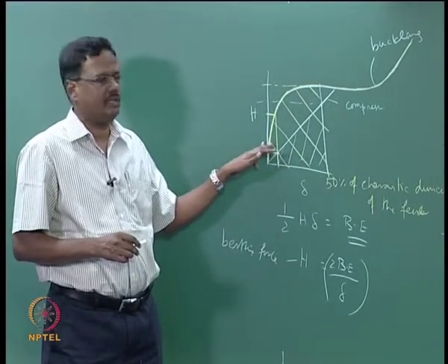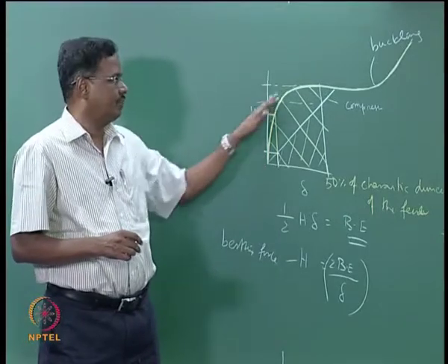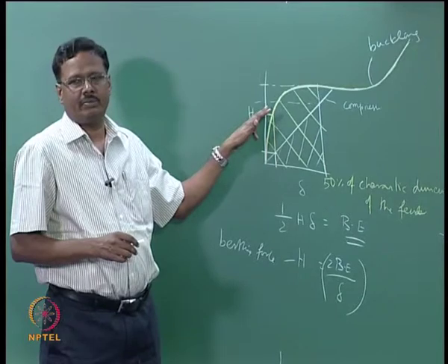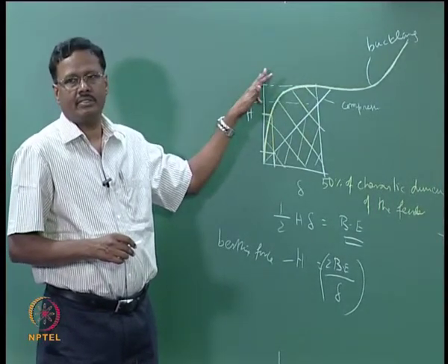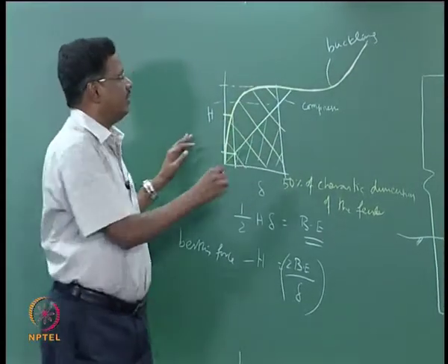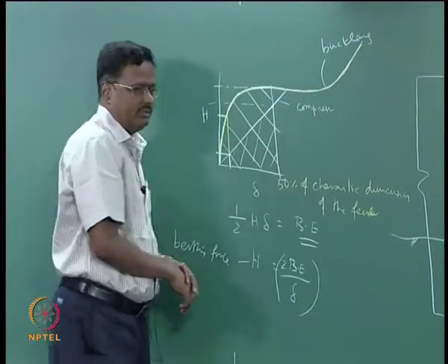Smaller vessel reaction will be less, bigger vessel reaction will be higher, whereas if we put this fender, smaller vessel also reaction will be high, it will not be very much less, bigger vessel also it will be very much high, and it should not go beyond this point. If it goes beyond this point, then this increase is very high, so we should not do that.